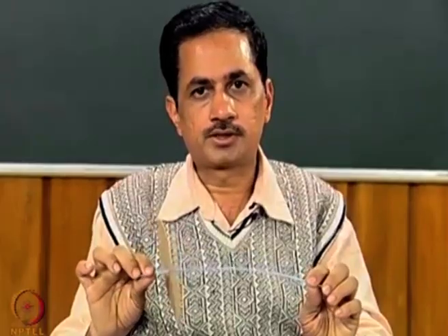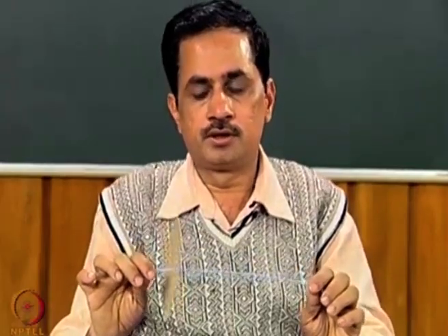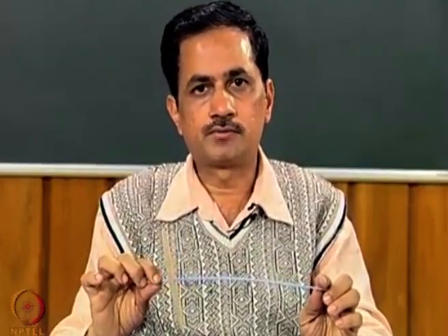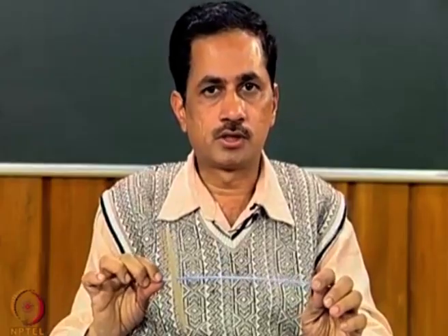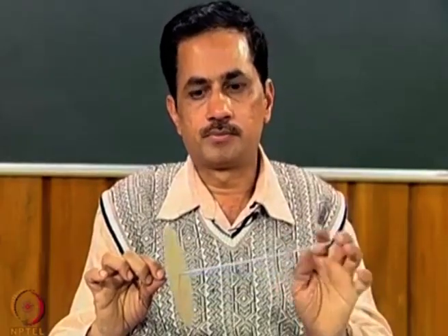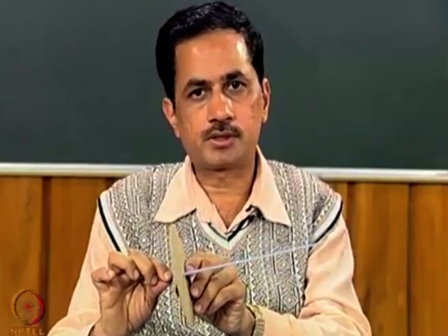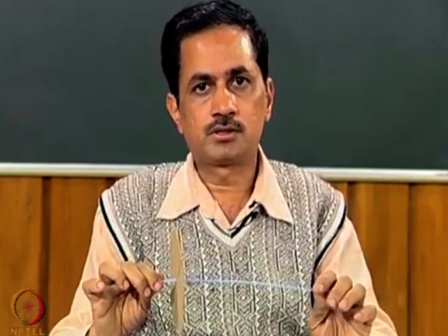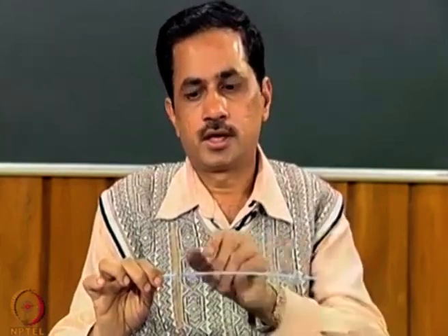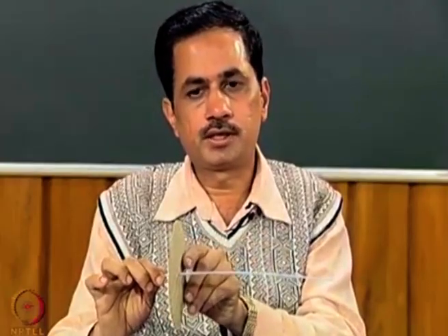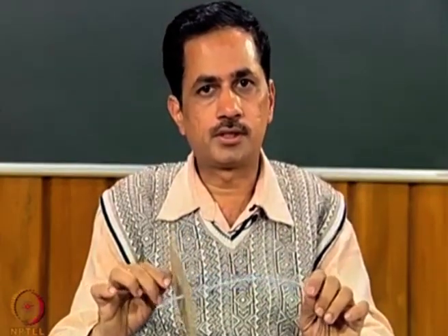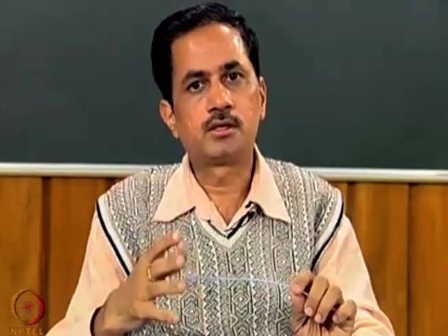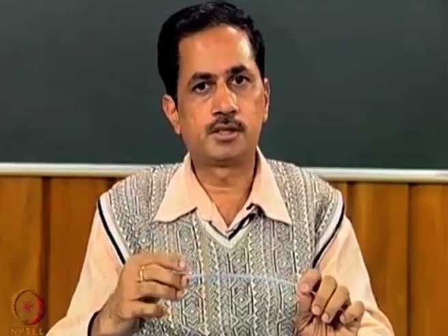In the subsequent lecture we will try to derive the equation of motion of this kind of disk without considering the gyroscopic couple, and initially we will take the 4 degree of freedom system and obtain the corresponding 4 equations of motion, that is 2 in the translational direction and 2 in the tilting. This tilting is different from what we considered initially in the case of the Jeffcott rotor, where we considered the torsional displacement theta.